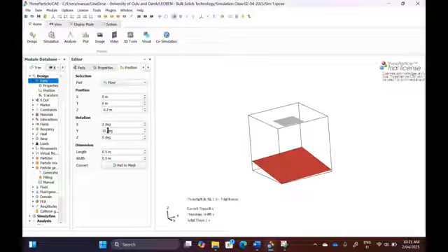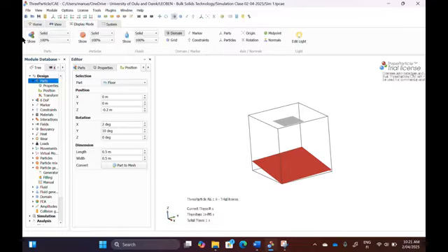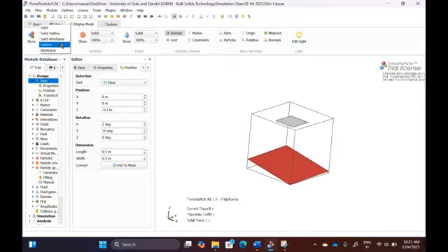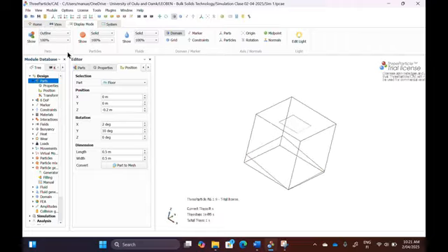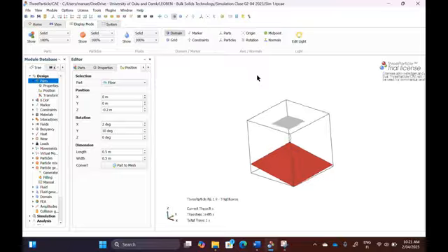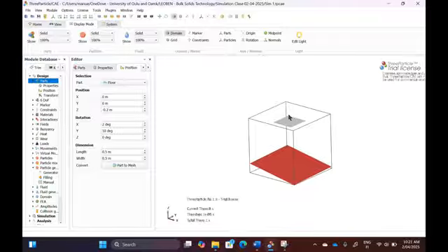Here is a hint. You can change the view here in display mode. You can change that you have an outline on your parts, which also makes them visible from the side. You can see that? If I change that to solid, I can barely see them, but if I change them to outline, they're better seen. This is only outline, I want to have it solid outline. There are different ways of viewing parts. For example, transparent, so I can see inside of the system. But let's come to that later. I'll change to solid outline. Also triangulated would be possible, but let's stick with solid outline. It's really cool for seeing the parts. Good. So far, so good.